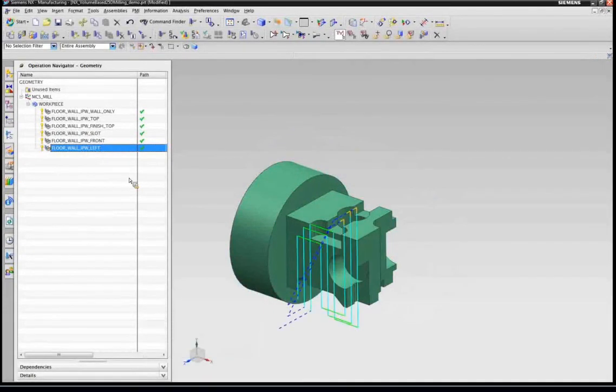The changes at the end were very rough, but what I want you to take away is that at no time did I create boundaries. I didn't have to change my boundaries because my change in operation sequence mandated something like that. Otherwise, if I didn't update my boundaries, my cutting wouldn't be efficient. I get a very efficient toolpath by just changing the sequence. My operations will adjust accordingly, cut very efficiently, and they're very simple and easy to define. So with that, I'm past my 20 minutes, handing it back over to Aaron.